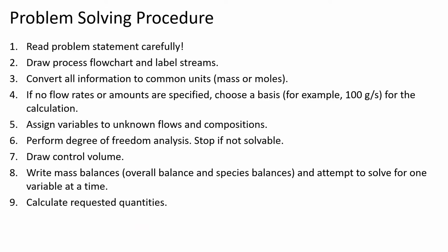The problem-solving procedure involves these 9 steps, and sometimes it's iterative. You have to go back and repeat the steps you performed. We're going to find that out. The first step is just to read the problem statement carefully. Then we had lots of practice drawing a process flowchart and labeling streams, and converting all the information we're given to a common set of units.